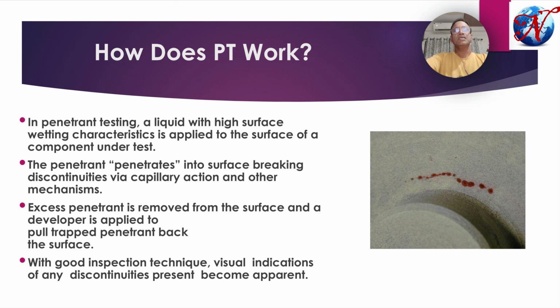Developer will draw out the blotting from the entrapped penetrant, and after drying the developer will produce a white contrast layer, and in the white layer you can identify the bleed outs of penetrant which are in a specific color of dye.